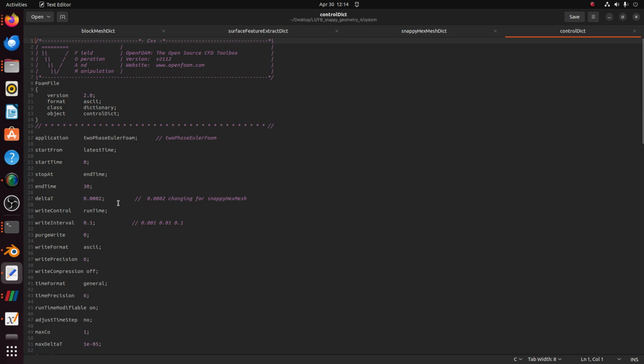Does changing the value of deltaT to a higher value have an effect on the mesh? No, sir. It basically represents that if we set it to 2, then folder 2 will represent the castellated part, then it will generate folder 4 which has the snap part, and then it will generate 6 which will have the add layers part also included.